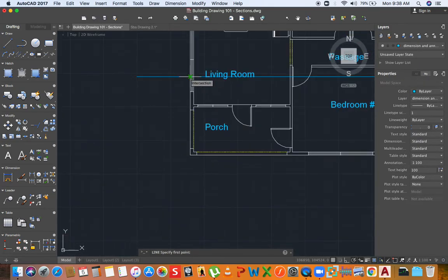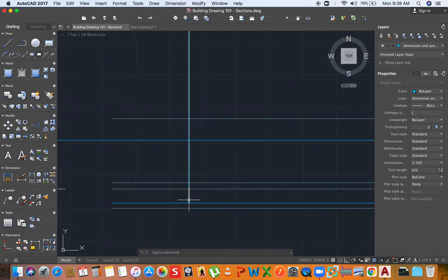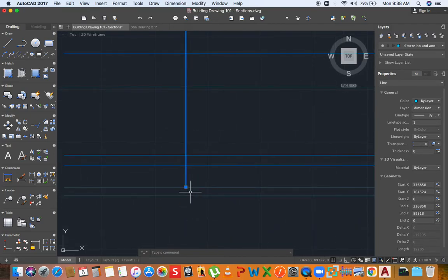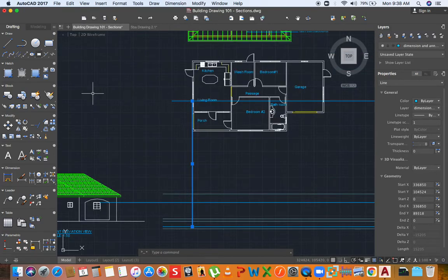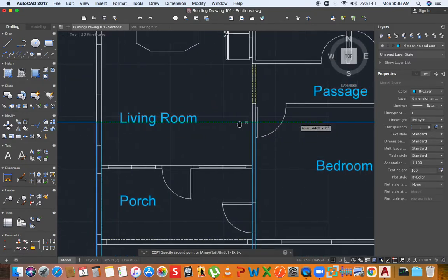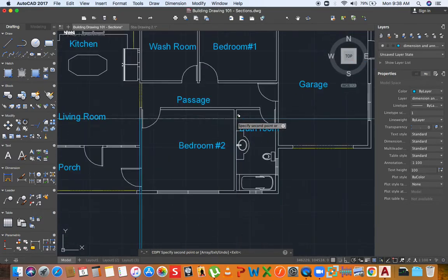I'm going to bring down a line to the second to last line, right? This line will represent the wall, and it starts from the top of the foundation footing. So I'm going to just copy this line that I've drawn from here, place it here, place it here. I'm just transferring the measurements for the walls, if you realize.